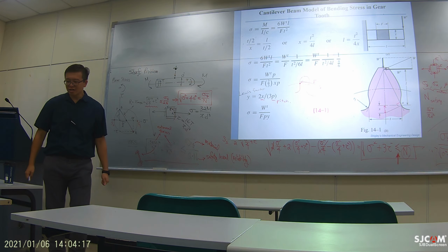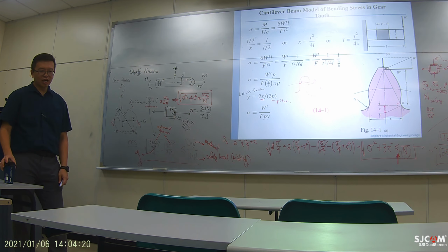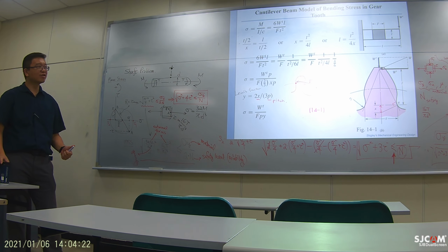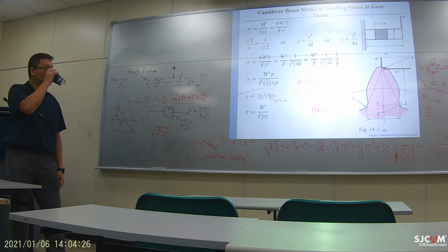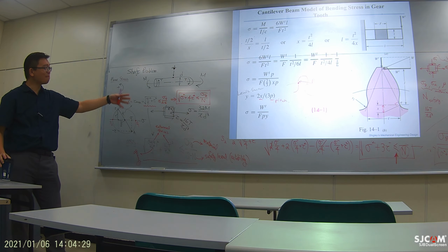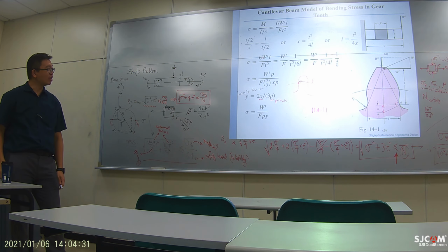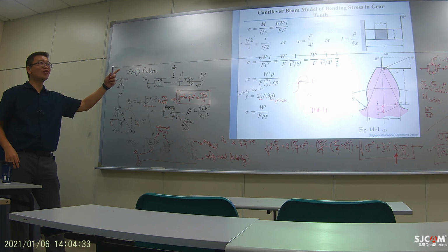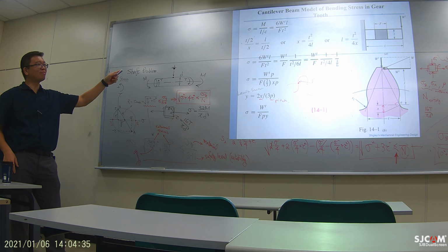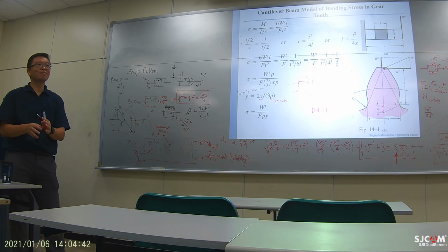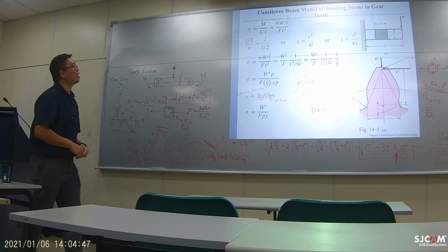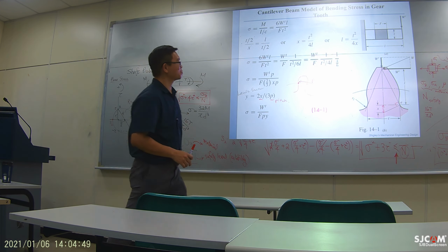So it's another characteristic length to describe the shape of the tooth. And it's defined in such a way that certain mathematical derivation can be properly simplified to a certain form, which is good for stress analysis.